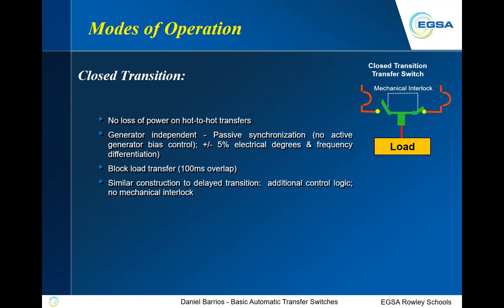In the case here down in Houston, Texas, we have to prove that if the transfer switch is connected to normal and you attempt to transfer to emergency and normal does not open, you have to reopen emergency and you have to trip a breaker within a half second. That will typically have to be demonstrated and proven to the local utility company.